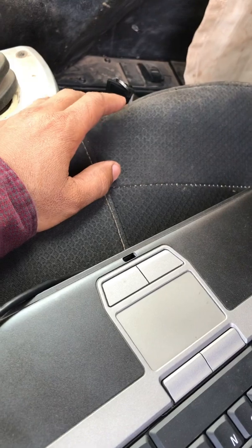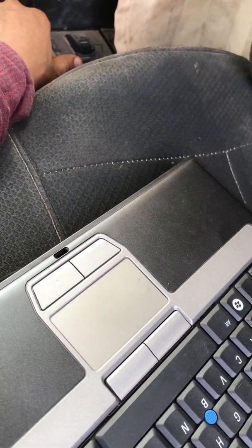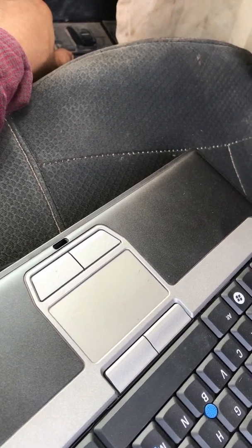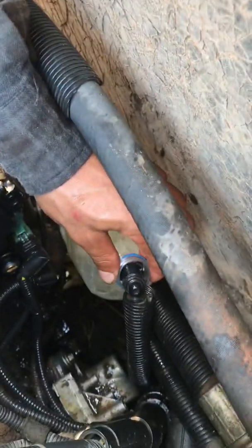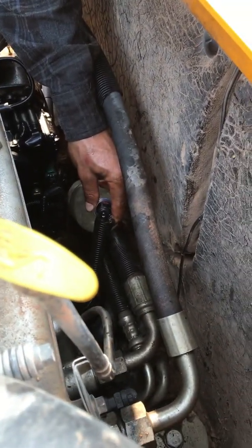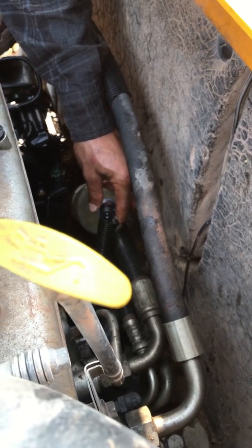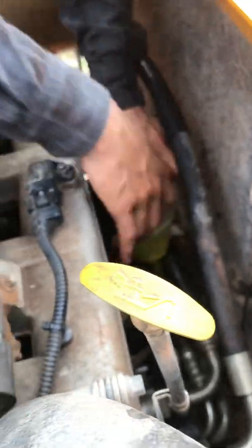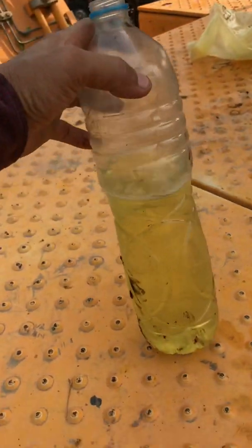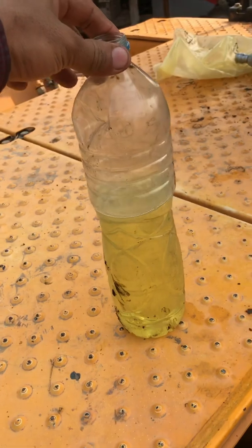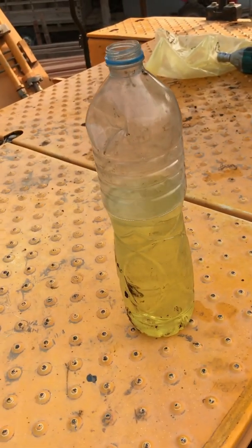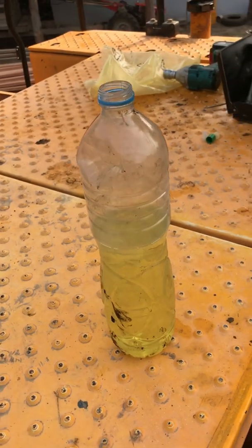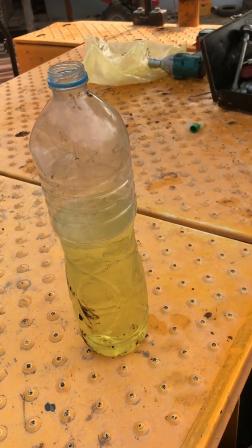Before I check the fuel injector, I will check the fuel system to make sure no air in the fuel system. Yeah, so key on and have a look. Now I'm checking whether the fuel pump is strong enough to pump or not. Okay, so I got more than 1 liter. So this is good enough. So there's no air in the fuel system. So I suppose the fuel injector has no injection. So I will go for the next step to check the injector.